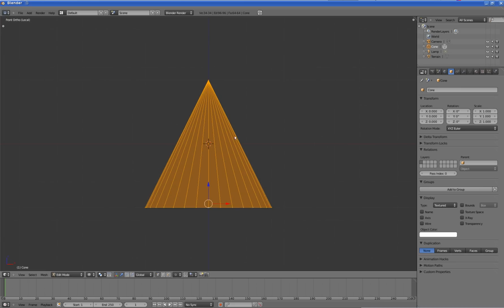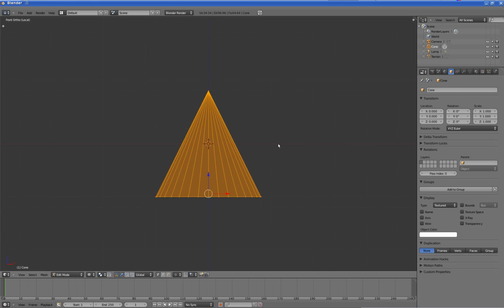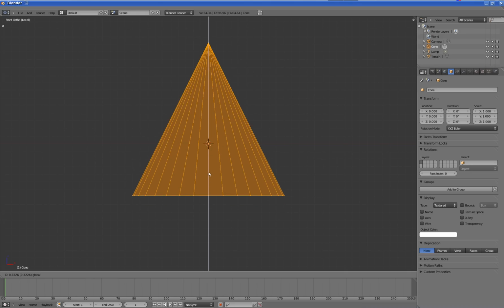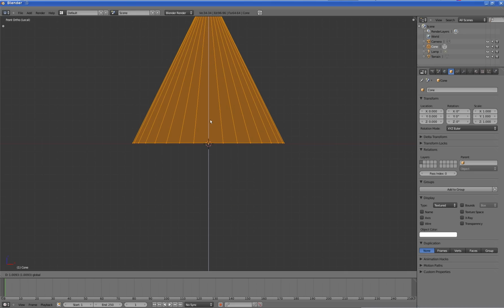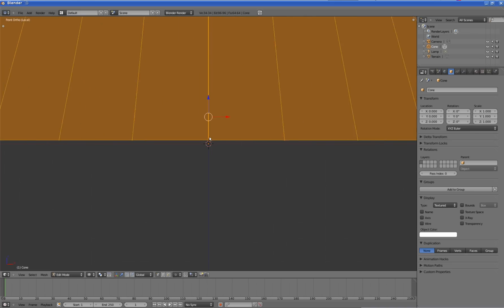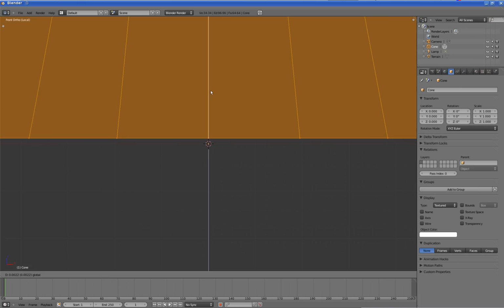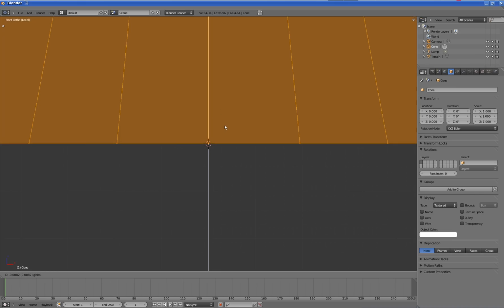Now let me enable the translate manipulator so that I can move this. This red line is our ground plane. Let me move all these vertices above. You'll notice that there is some adjustment to be made. For fine-tuning translations, I first select the translation handle, move it down, and then hold down the shift key.